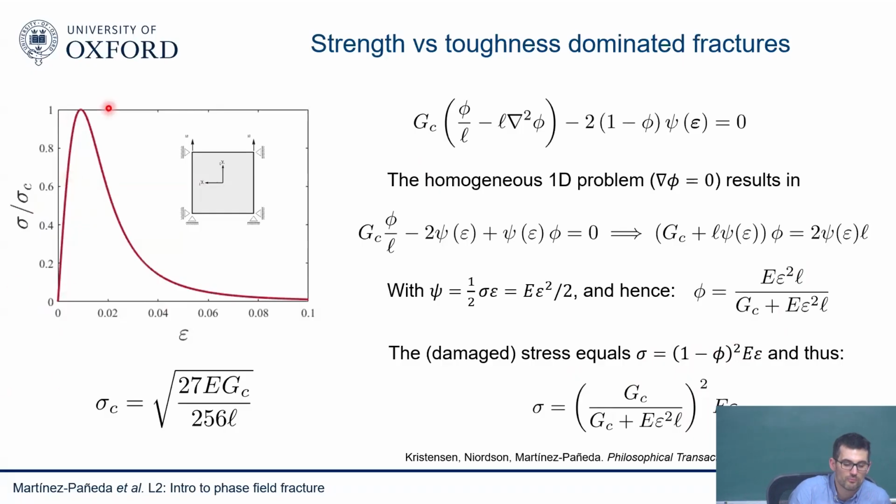Those of you familiar with cohesive zone models or some of these damage models will also recall seeing something like this. It's kind of a traction separation law. So your stress increases almost linearly. Here you start seeing some nonlinear phenomena. Eventually you reach a strength, and then you get some sort of softening degradation until you get a complete failure. This is the idea. So it's kind of a traction separation law in a cohesive zone model.